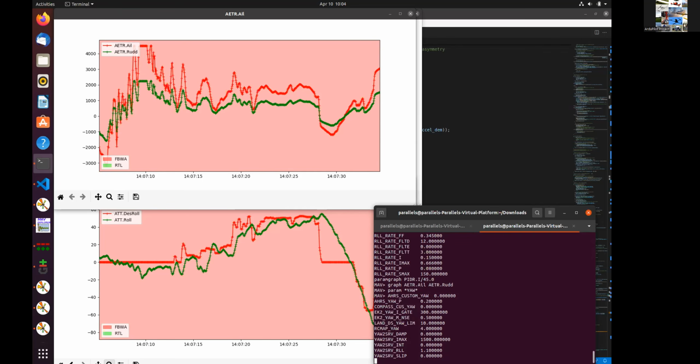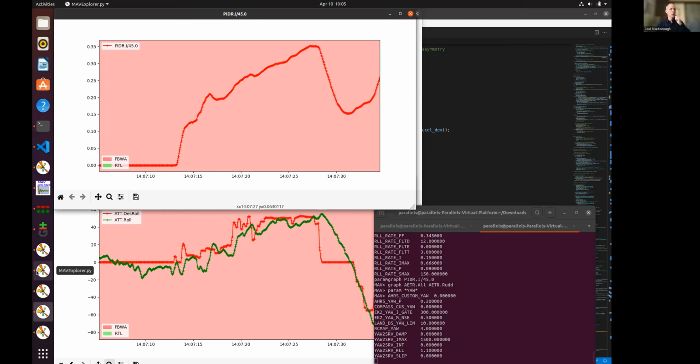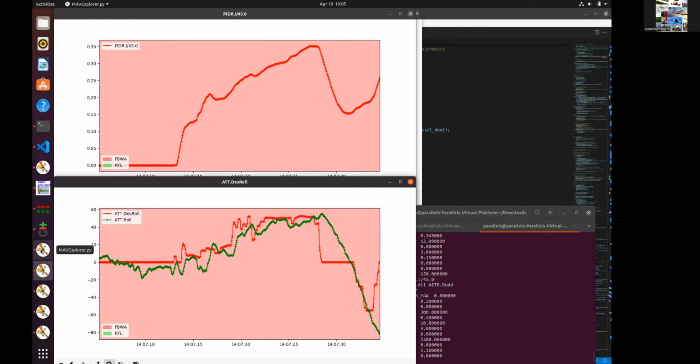And we haven't got the frame parameters. A Believer is probably common enough that we should just have the tuning parameters up as a thing to download. We actually have a wiki page, I think, which is hanging there waiting for some love. The Believer is definitely a common enough frame for fixed wing tuning parameters. Of course, it depends on the throws you've got, and people set up different throws on the same airframe because they use different servos, or the clevis is in a different hole on the control horn. We don't have control over that.